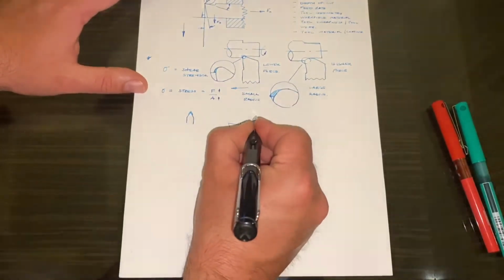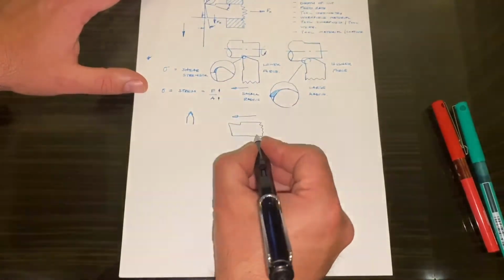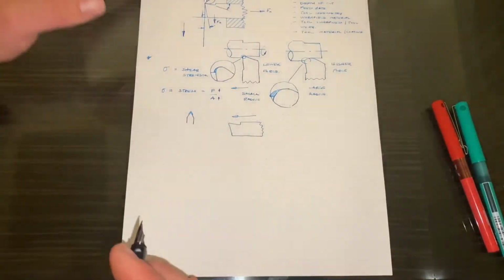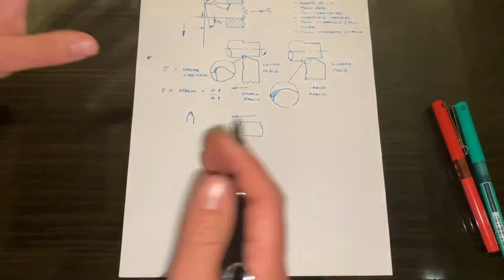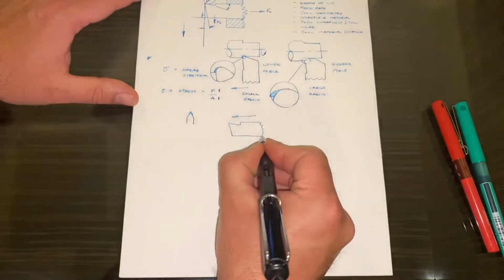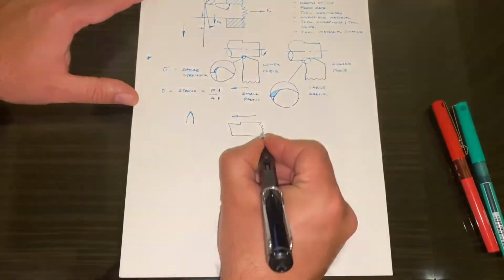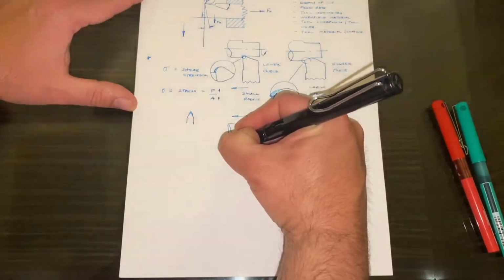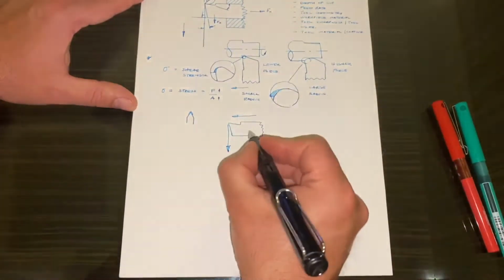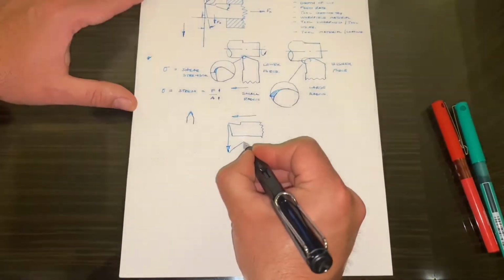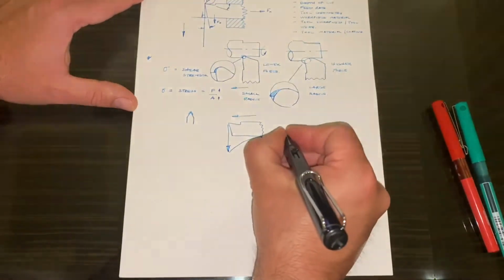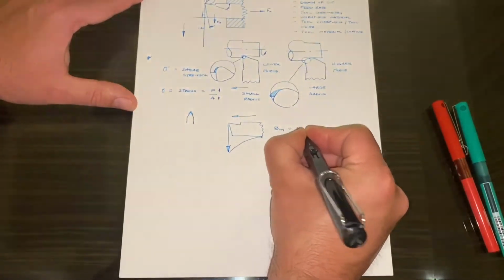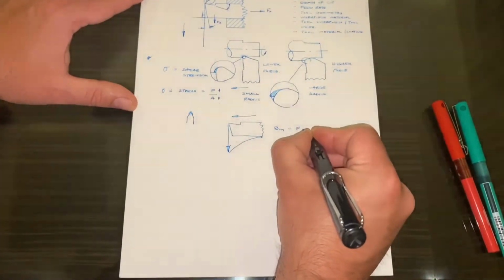So the longer this tool hangs out from the tool holder, the greater the leverage. The greater the leverage that force has to act upon, the higher that this potentially can deflect. So from the point where it ceases to be supported by the tool holder, if there is a force acting down on the tip, and there is when it's under load, then there is a bending moment applied to it, and the bending moment is equal to force times the length.